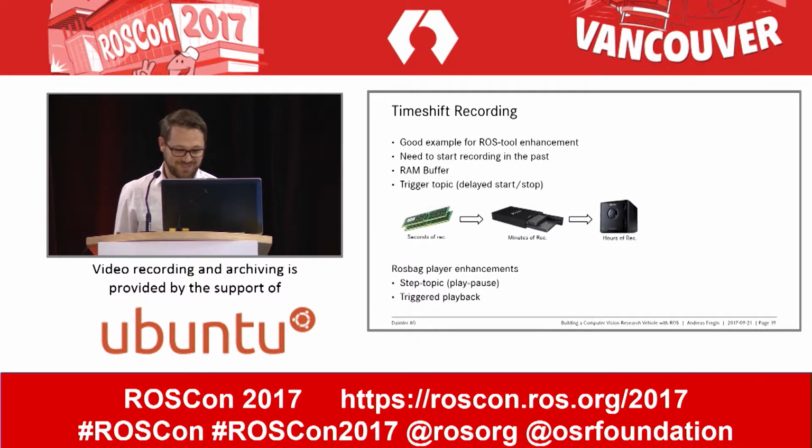Our solution was to modify the bag recorder so that it continuously records into a RAM buffer and exposes a recording trigger topic. The operator can then request to start recording from some time in the background, in the past, sorry. And as long as this past data is still available inside the potentially very big RAM buffer, you can also dump scenes from the past to your disk.